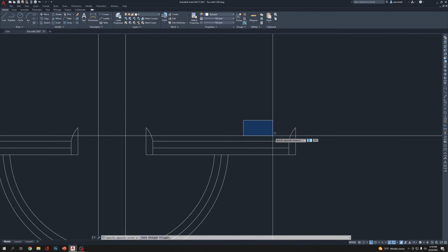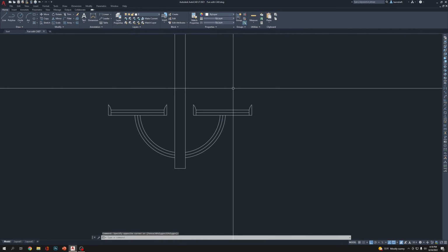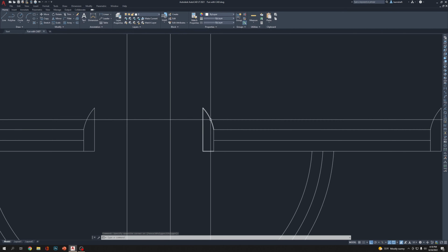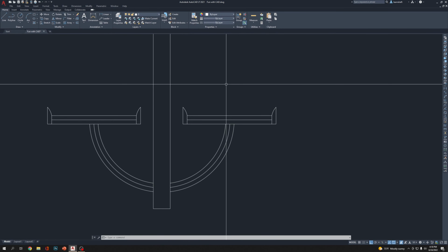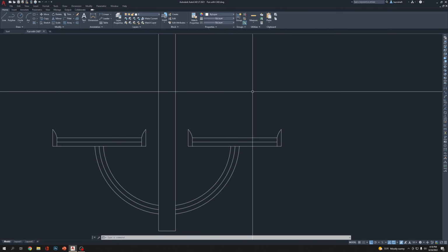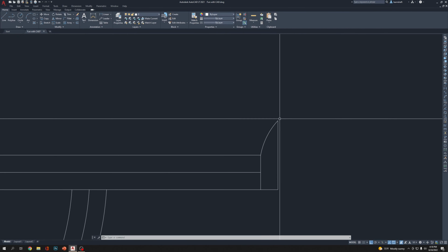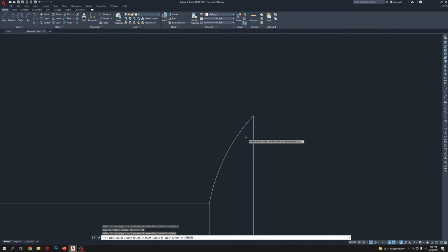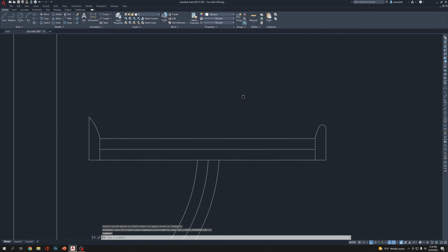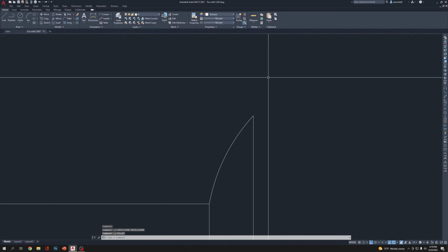So if we keep something there, it's not going to fall down, even if there is some slope, it's still going to have some support. And that's good, I think. Do you think this is too sharp? Somebody could get hurt. Let's fillet, radius 0.25, enter, select here, click there. Okay, now a problem. Control Z, fillet, enter, radius, enter, 0.125.